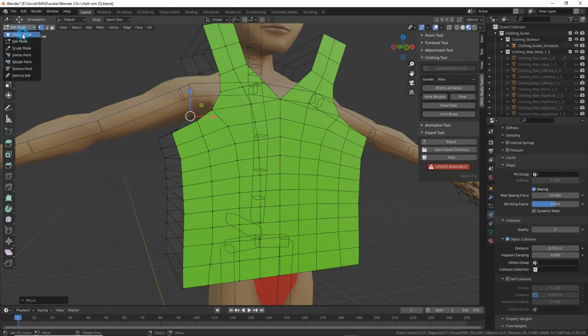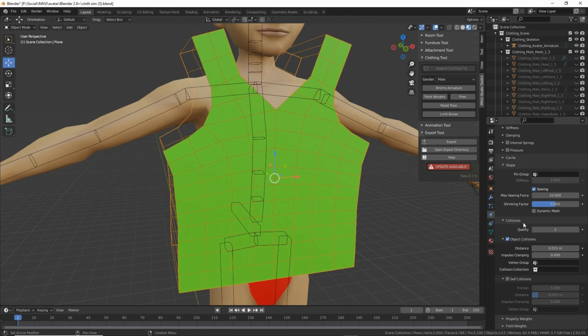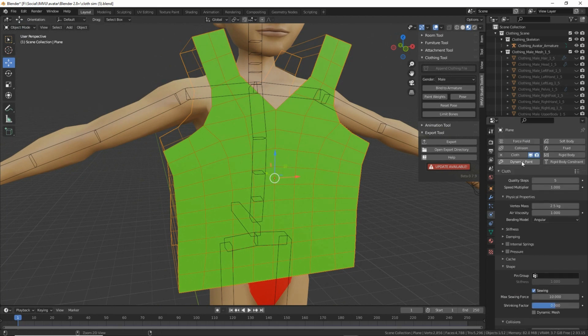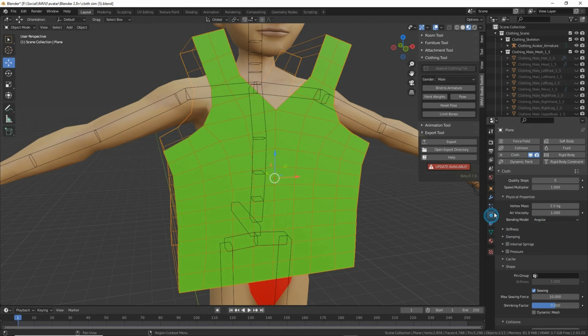So, just to recap, once we've got our object, our core settings, once we've assigned the cloth modifier, so the cloth modifier, physics properties, so check to make sure that cloth is enabled. Our basic properties are to set physical properties of the mesh itself, so that physically how heavy our cloth is.